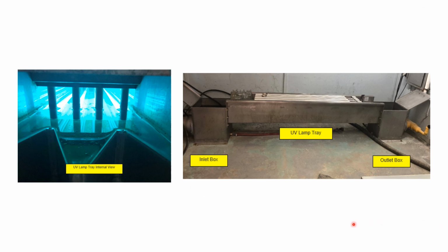For the pilot study, I placed a sump pump in the outlet box and flooded the outlet box, inlet box, and lamp tray with 168 liters of water. The discharge line from the sump pump was then routed back to the inlet box. In this way, I was able to continuously recirculate the inventory across the UV lamp tray during my test, which lasted 24 hours. Again, the water source I used was turbid, so I pre-treated with electrocoagulation to remove the solids. In this case, I used one of our larger industrial size EC units to do that.